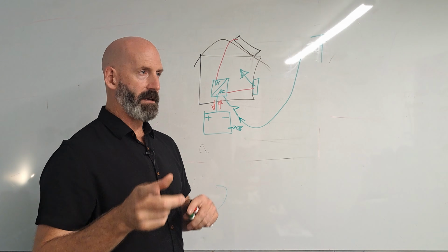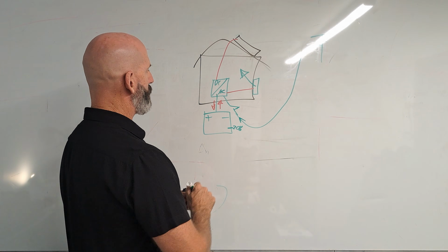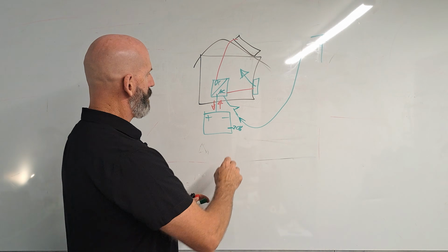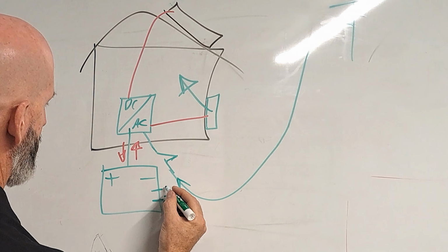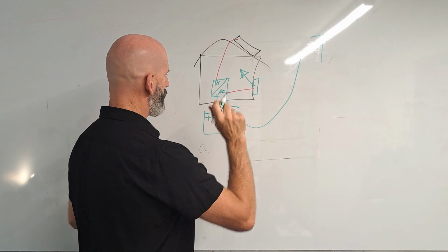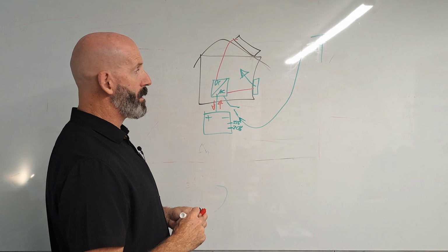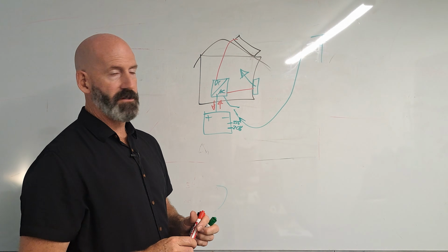Unless you're running Selectronic in a hybrid mode, whole other conversation, they can do it. But ultimately, these are just acting as a battery charger. As soon as that battery is back up to, let's say, in our standard systems, 35%, then it says, cool, we're at 35%, I'm safe again, disconnect the grid, get rid of it. And so now you're not electrically connected to the grid. This has several advantages.